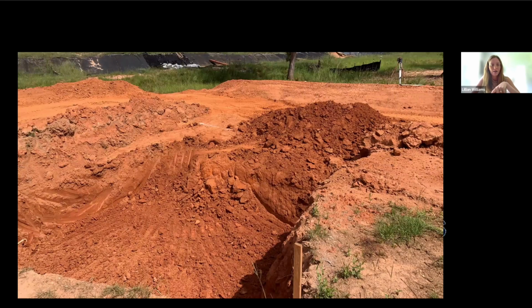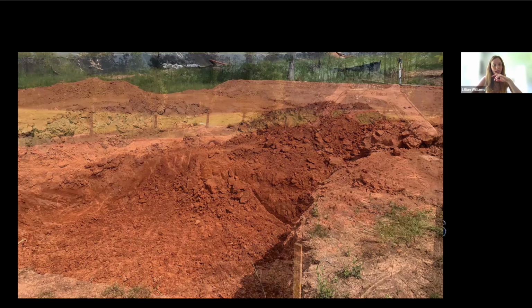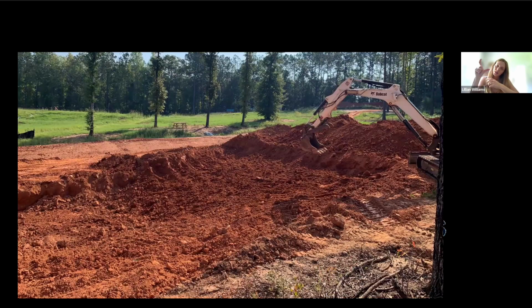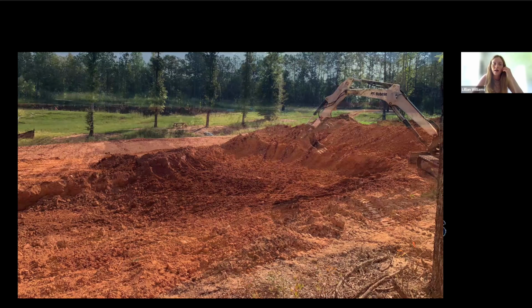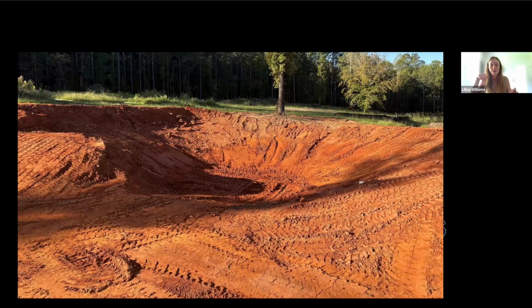We dug it down according to the depth that it needed to be. Then we would cut the side slopes as we're doing here. You can see that little ledge, and I mentioned the topography. The ledge dropped us down to get to what the actual height would be instead of us completely cutting back the entire way. So that's how we managed the work there. And this is kind of the final product with the correct basin length and width according to the plans, the mouth of that sediment trap, and then the side slopes.